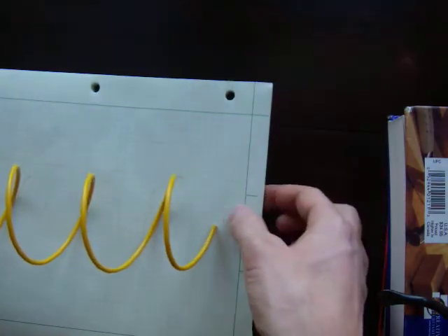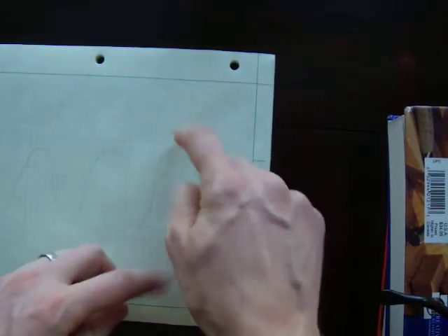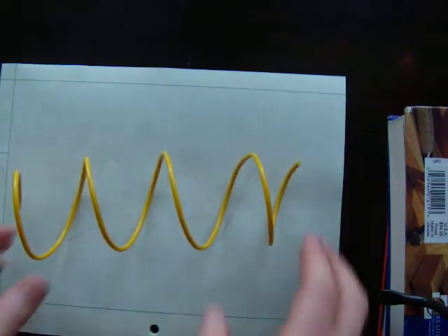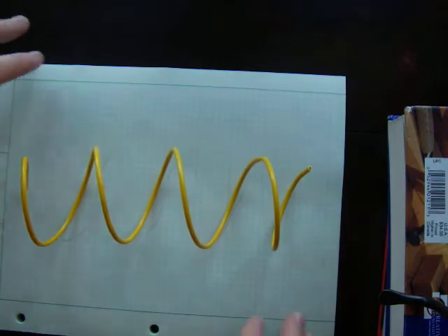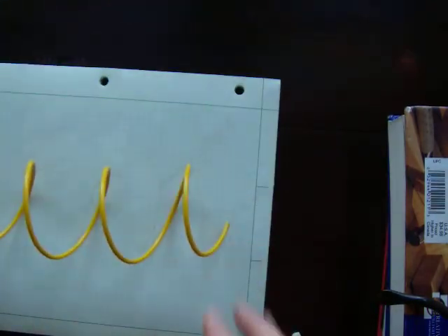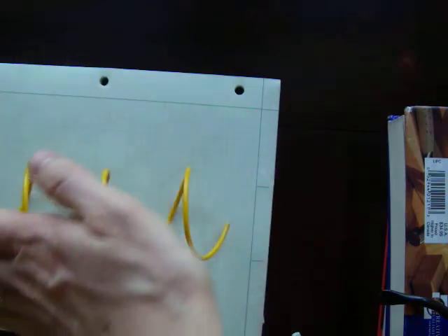So we do the complex conjugate to take this thing and flip it over. When that flip is done, this peak is now facing down, which is where it's supposed to be. So the complex conjugate is needed in this equation if we're working with complex numbers. A flip in time causes an inversion in the imaginary space.